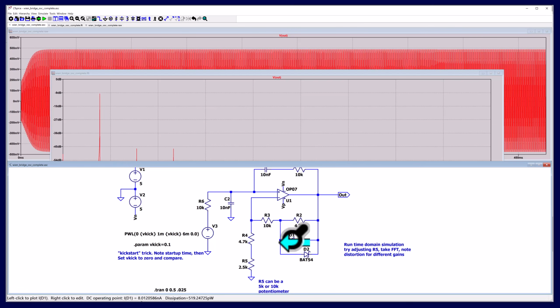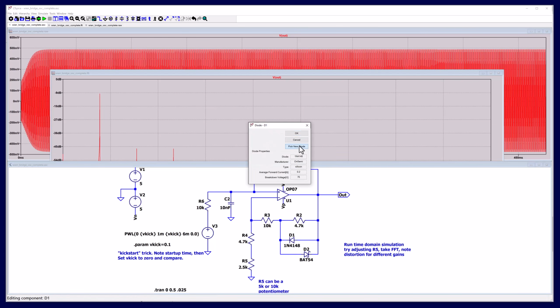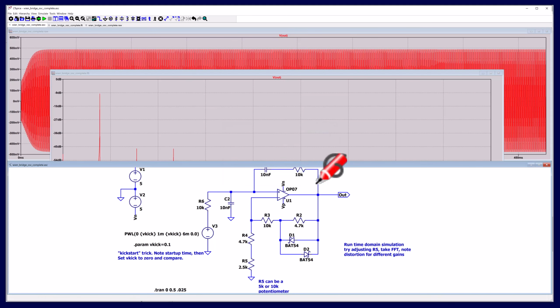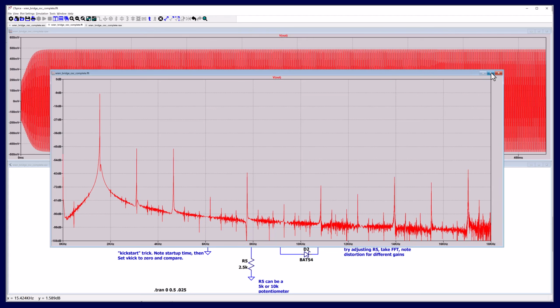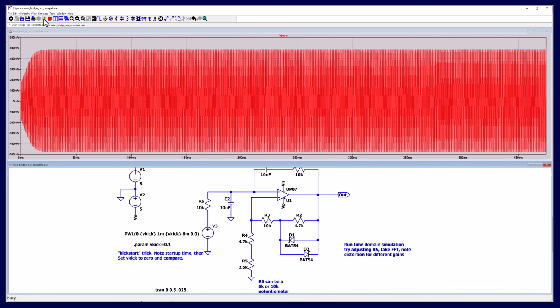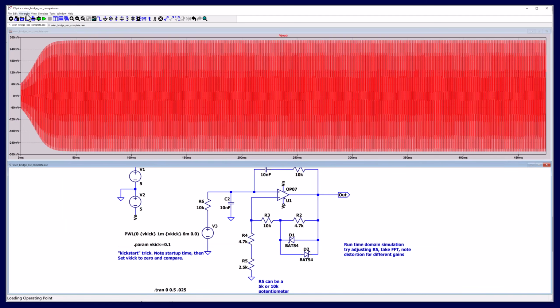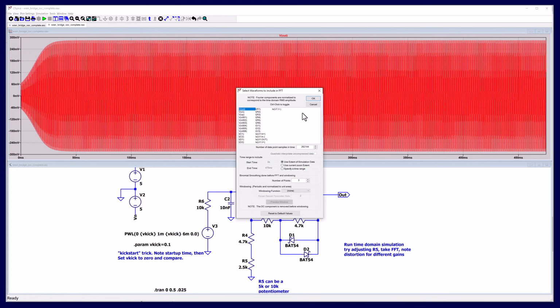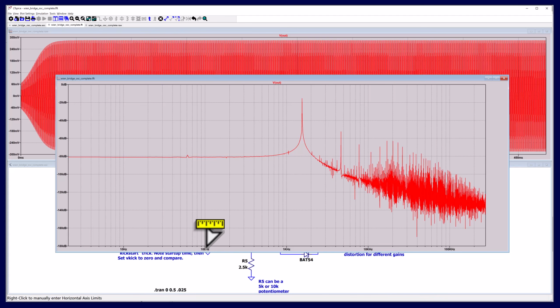And then vice versa, let's do the same thing. Pick new diode. If I make this guy a Schottky diode again, okay, I expect my third harmonic to be pretty terrible, but I bet that second harmonic disappears. Okay, so let's run this again with 2 Schottky diodes. And now view FFT. Yes, please. Linear axis.